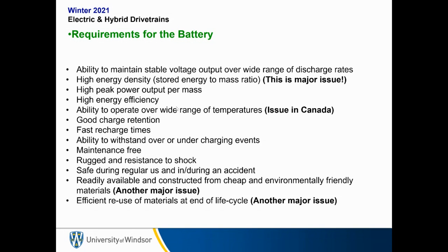Has to have a high energy density. This is the ratio of stored energy to mass. Now this is one of the biggest concerns with batteries. When we look at hydrocarbon fuels, their energy density is almost an order of magnitude higher than most batteries used in automotive applications today. This is one of the major issues keeping widespread electric vehicle adoption at bay, is that if you had to carry a battery that could give you, say, 1,000 kilometers of range in a big SUV, it would weigh so much that you would have to have double the size of the electric motor to drive the vehicle.